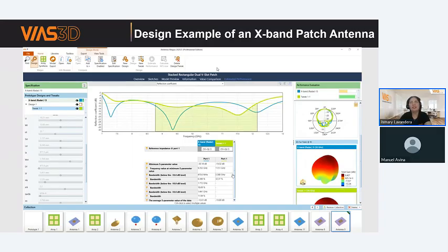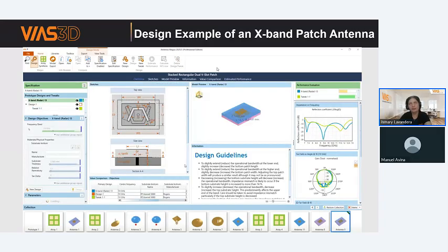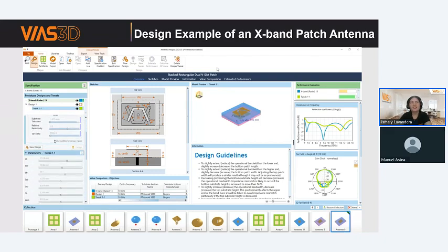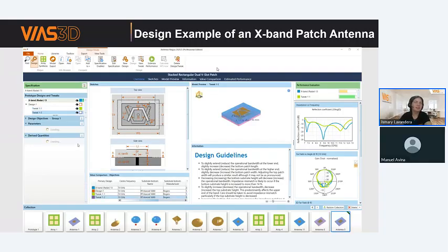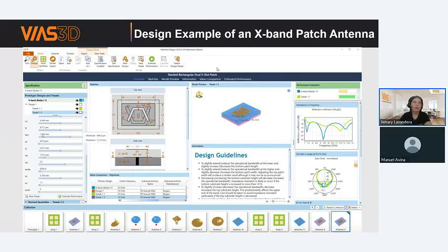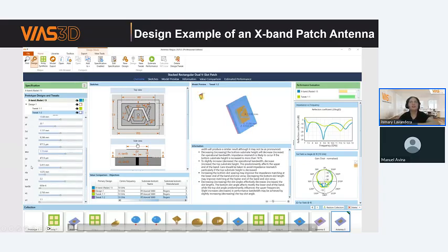And if you see, I get a better performance in the range of frequencies that I'm going to design. But still, I want to improve it. I want to get better performance. So I will create a new tweak. I just want to show you all the steps. I know that I should decrease a little bit this value here of the width. As you can see on top there on the overview, we can decrease this slot width.